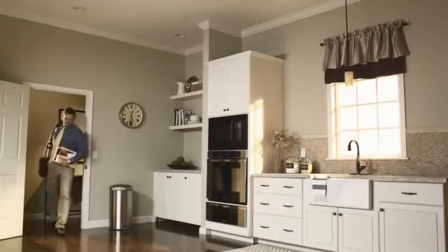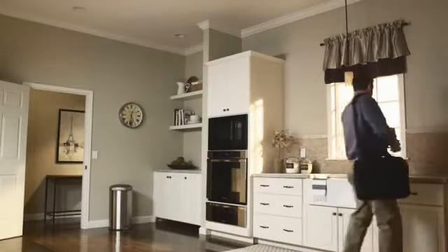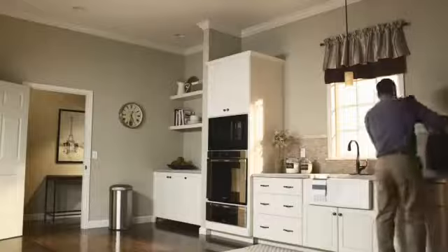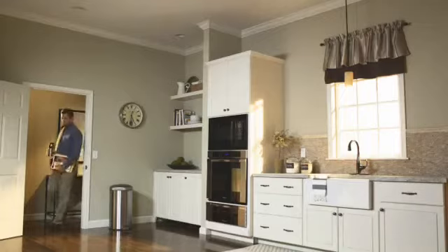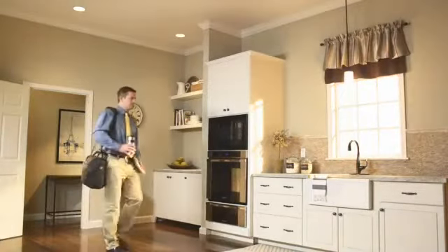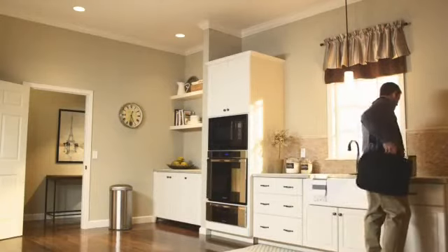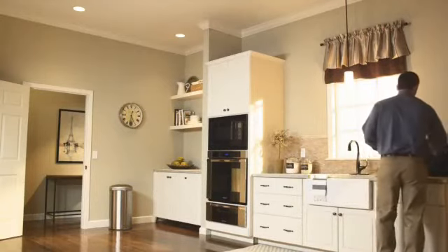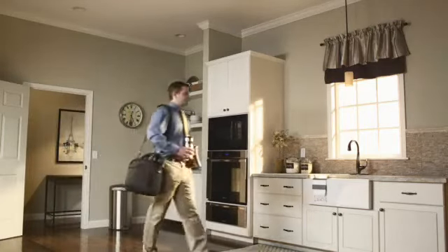Daylight sensing mode also has the added function of learnability. If you walk into a room and the sensor doesn't turn the light on, but you want more light, simply manually turn the light on within 5 seconds. By doing so, the sensor will learn that you would like more light in the room. Conversely, if you enter the room and the sensor determines there isn't enough natural light and turns the lights on, but you want the lights off, you can turn the lights off manually. The sensor will learn that you would like less light in the room.